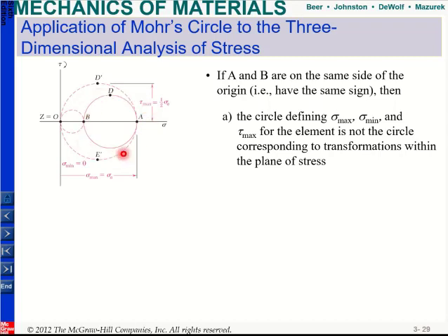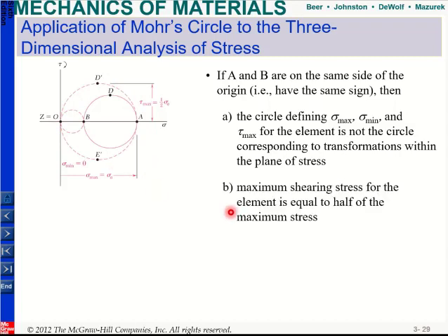In this case, you will construct this Mohr circle. When you construct your Mohr circle it will look like this. So you have A and B, and you will find it somewhere there. But since we are in plane stress, I know that my third principal stress is 0. Which means that actually I have these two additional Mohr circles. So when you find your shear stress, if you only consider this circle, you will find that it's equal to the distance from here to D, and it will be your maximum in-plane shear stress.